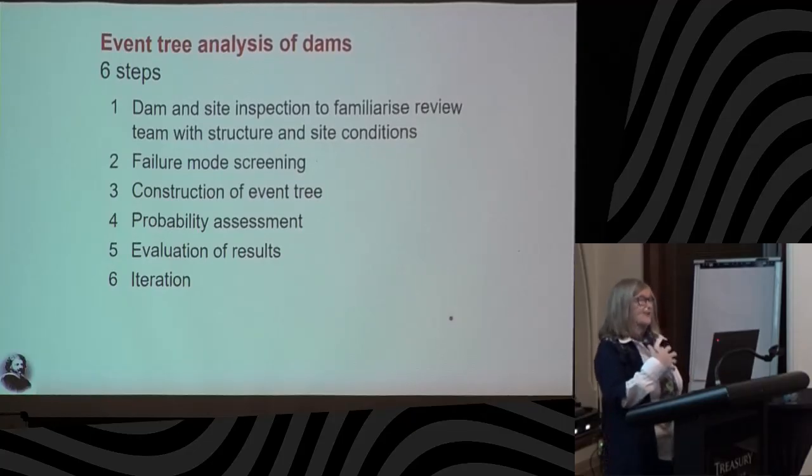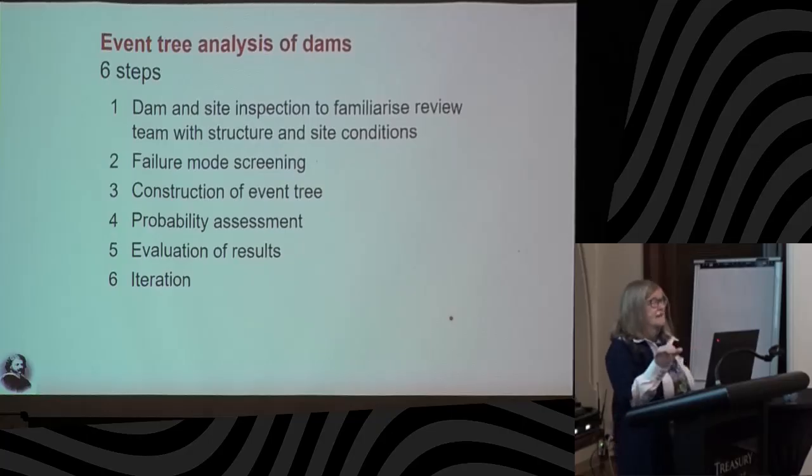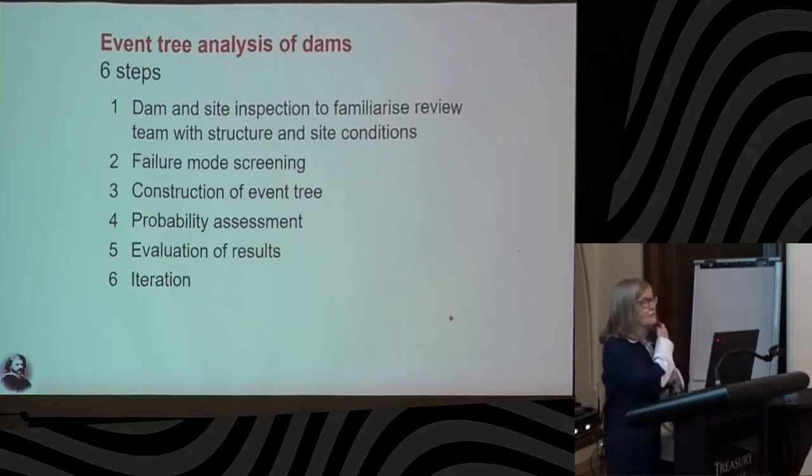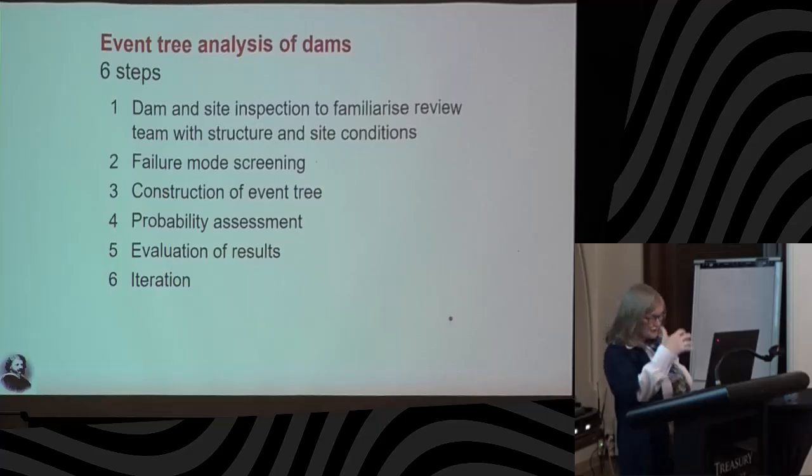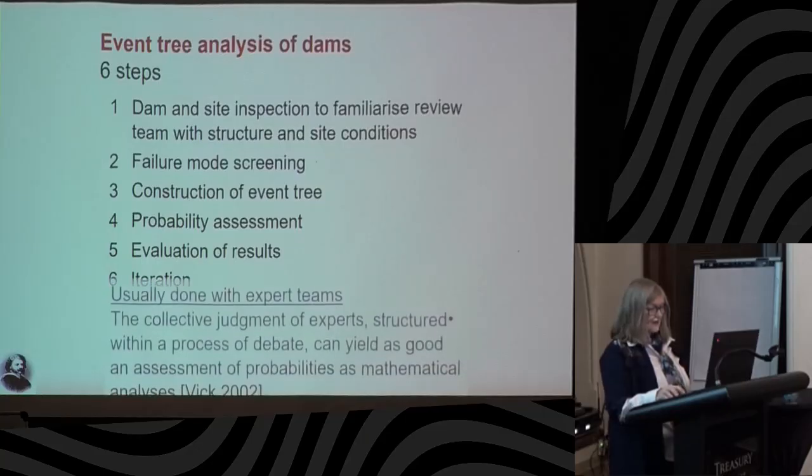It involves inspection of the dam, and then you make a big list of all the possible failure modes that could happen, and then you prioritize among them. You construct an event tree, which I will show you, and then calculate probability, evaluate the results, and you always do an iteration or two.